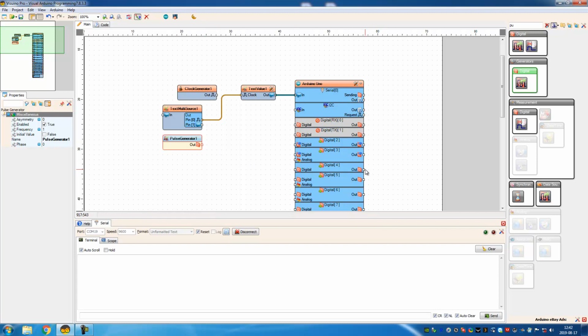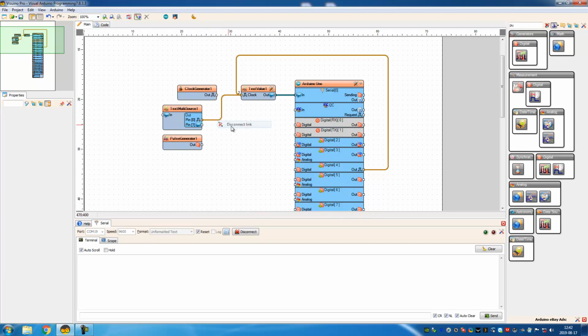So if you have a button, for example, and take that one over there, let's say you have a button, you see it's gonna be a clock symbol. It's not necessarily gonna be acting the way you want, because you might need to push and release a button, and some buttons are gonna stay down. So in those cases you might need to use a detect edge.